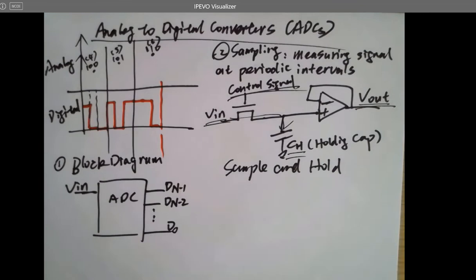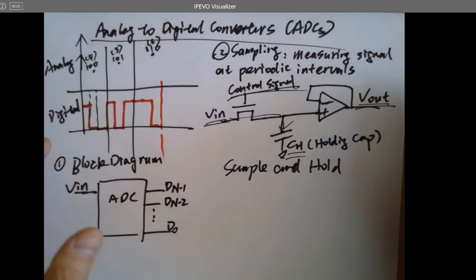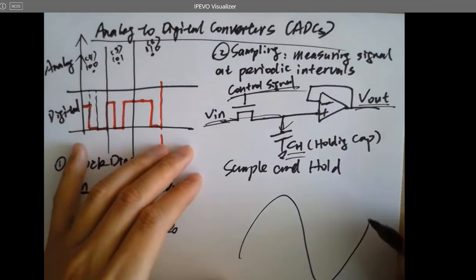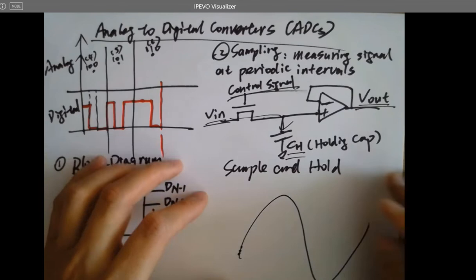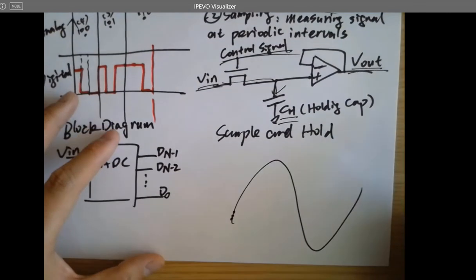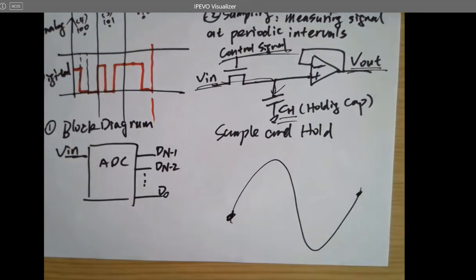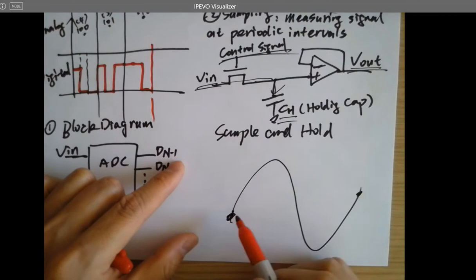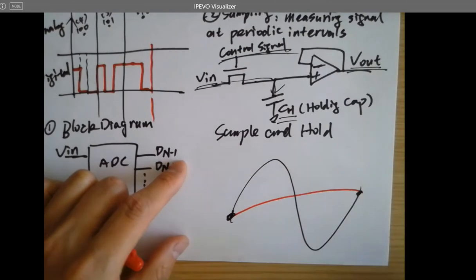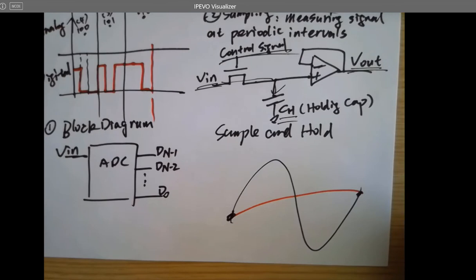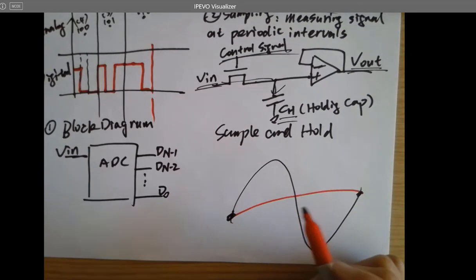It's like there are so many points. Just grab one and take your time to convert it into a digital signal, and then grab another one. You're going to miss some of the points. But if you sample quickly enough, it's actually fine, because you can imagine if you have a sine wave like this, sample here, sample here, sample here. Does that matter actually? Doesn't matter. What matters is you sample 1 point here and sample another point here. So when you recover it, the computer is going to treat this signal as this. It's called aliasing. That's an incorrect frequency being recognized by the ADC.